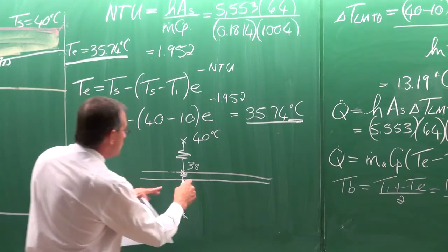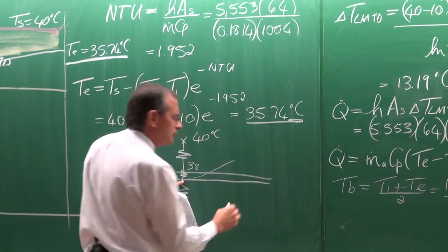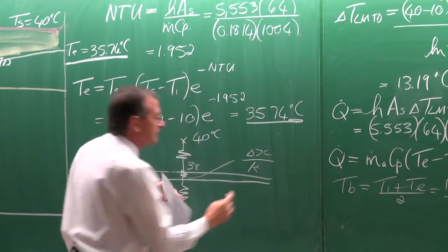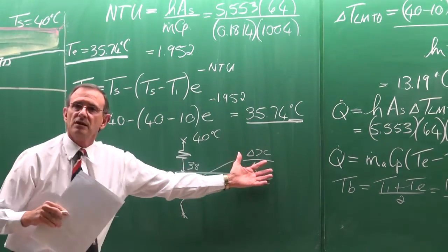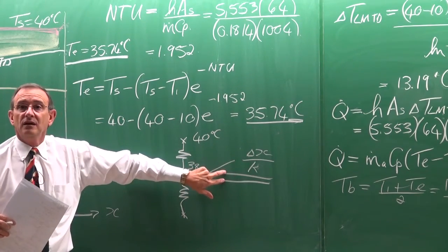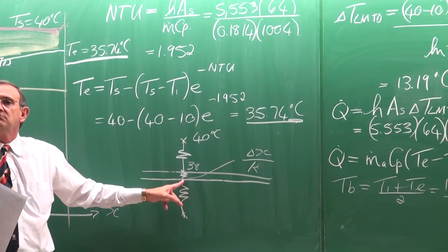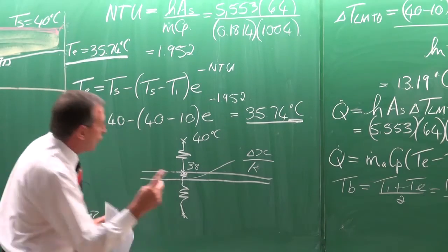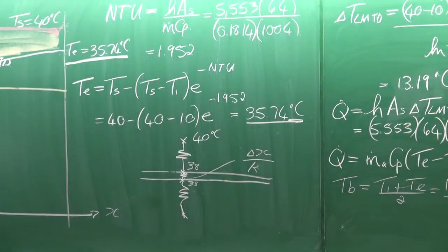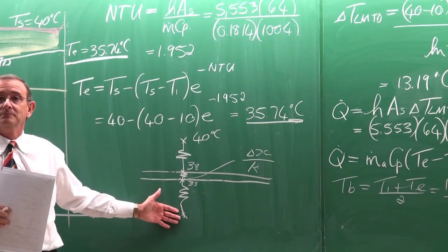So for this one, if you look at the resistance, it is that term of delta X with a K underneath, thermal conductivity. I can't remember the rest, but it's driven by those two terms. That one is very thin, and the K is very high. So the thermal resistance of that is negligible. For all practical purposes, the temperature there on the inside would then also be 38. Okay. So it becomes a little bit more complicated, but we're going to get there.